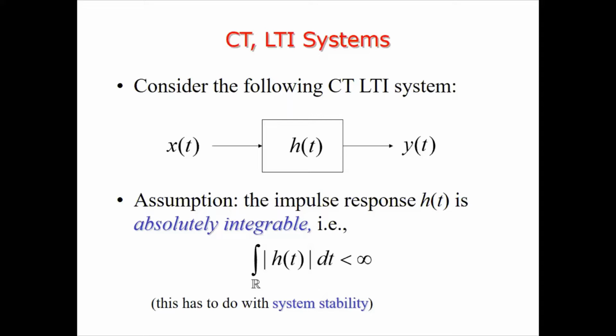If I rearrange, C of S equals G of S into R of S, where C of S is nothing but the Laplace of the output. So C of S equals G of S only when R of S is unity, and R of S is equal to unity only for the impulse function.